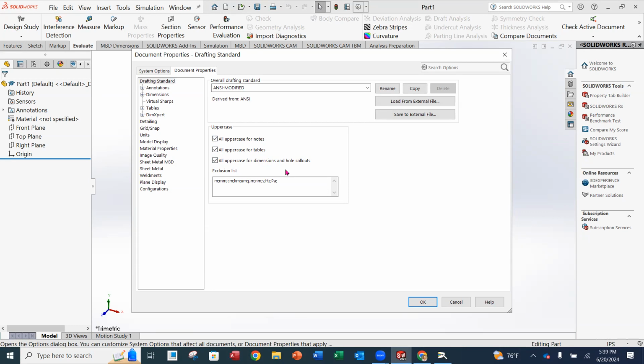If you don't do that, I don't know why, by default, even though neither of the standards, ISO or ANSI, we all do capitals for everything on drawings, it'll come in with lowercase values. So put uppercase for everything.